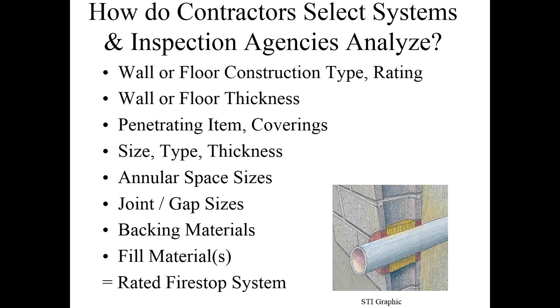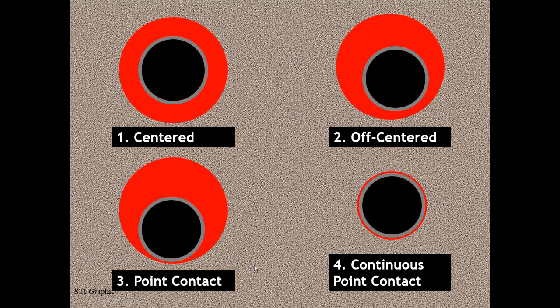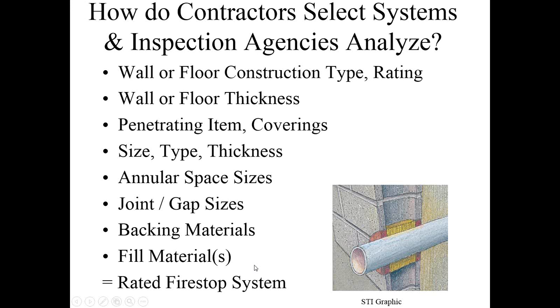What section in IBC will tell me floor penetrations going into open air areas, pool decks, balconies, require fire stop? If you get back to the International Building Code, the International Building Code calls for continuous fire-rated assemblies, regardless of what's happening on top of the assembly. So if it's a 2-hour fire resistance rated assembly, and the penetration is open to that next assembly, that continuity of fire resistance has to be there, period.